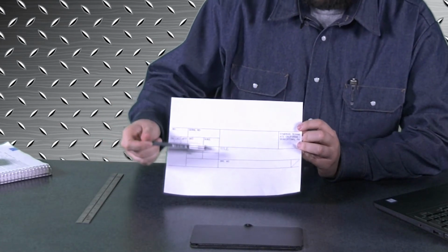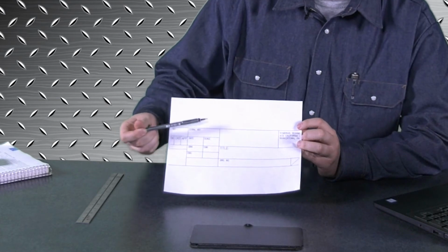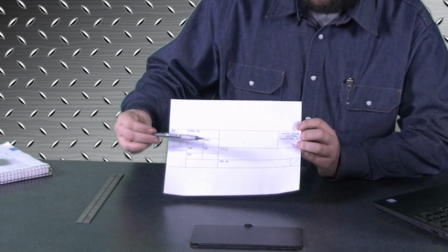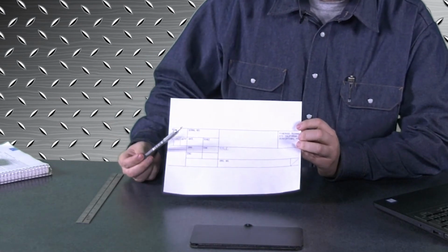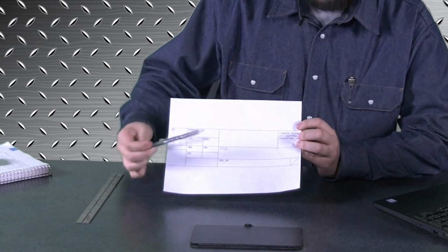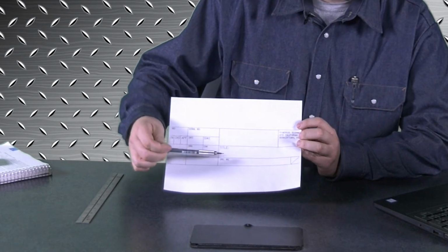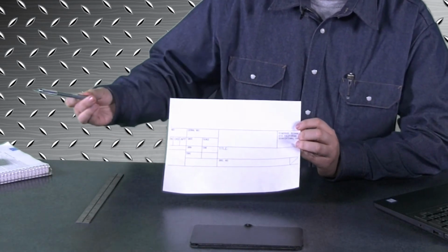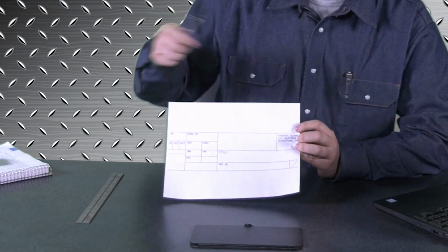So these are the two things you always need to check first whenever you get a print or whenever you're asked to build a part. Reference your work order. Do I have the right part? Do I have the right part name? And then go over here and make sure your drawing is the current drawing number or revision number. If it's not, you'll be building the wrong thing entirely and you'll have to go back and redo all your work.